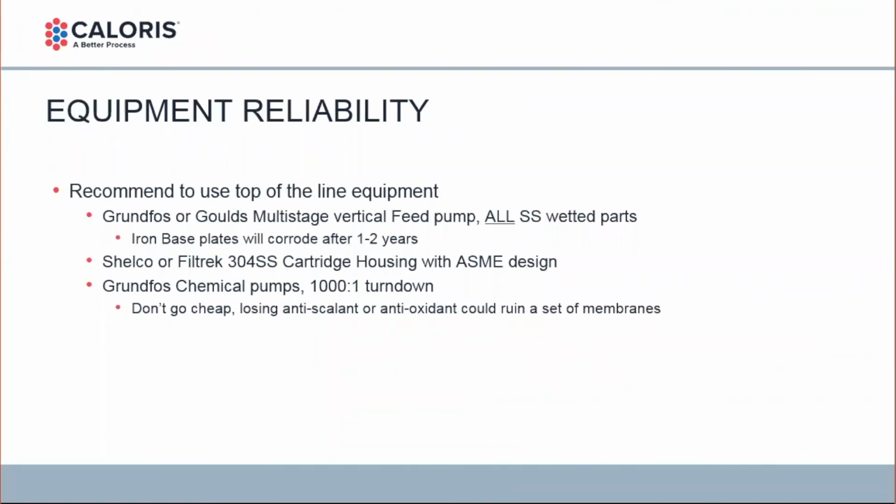Equipment reliability: definitely use top of the line equipment for your feed pump. Use an efficient Grundfos or Goulds multi-stage vertical feed pump. Make sure you use all stainless steel wetted parts. I've seen some iron base plates that typically corrode after 1 to 2 years, and then you have to replace it already.